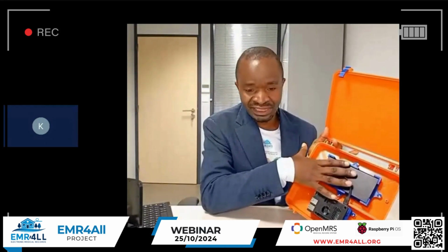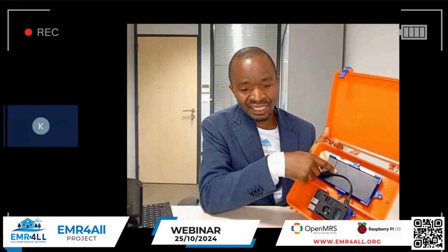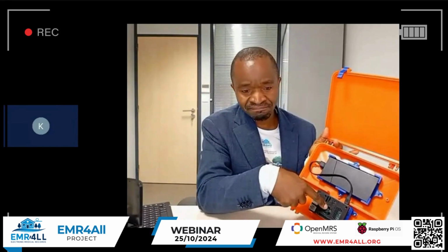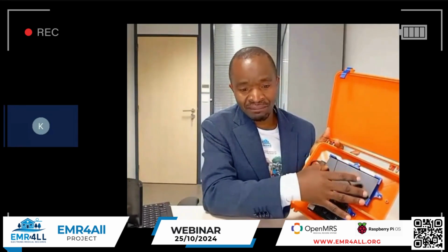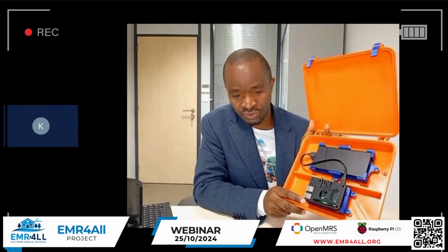We put it in the box and associate it with a power bank. The power bank serves to run the Raspberry Pi so that it keeps the power uptime. We also chose a type of power bank called pass-through. Pass-through power bank means you can charge the power bank while it is being used.